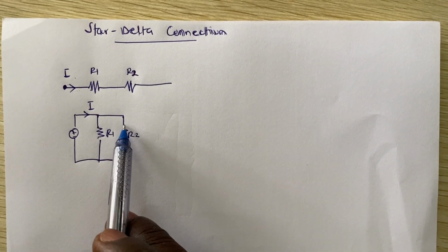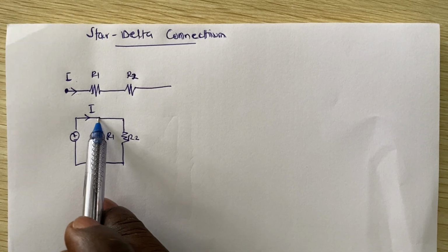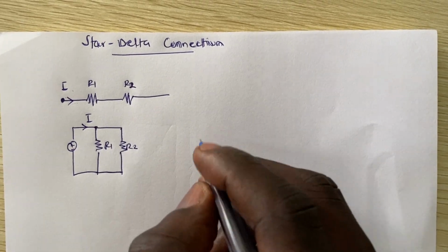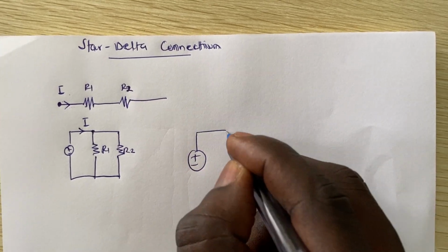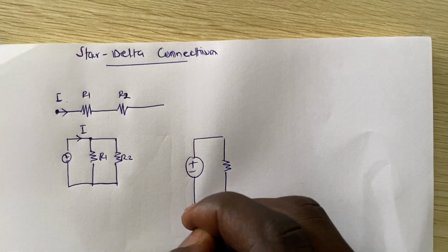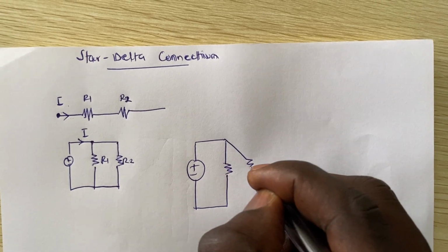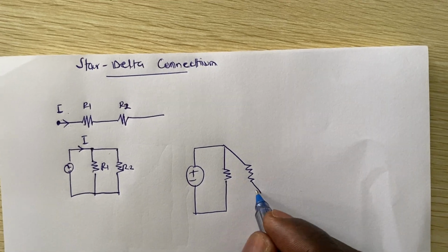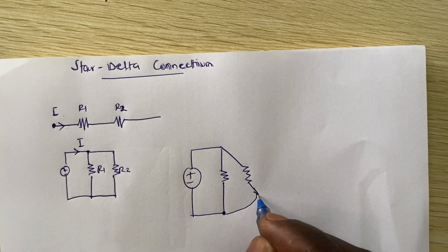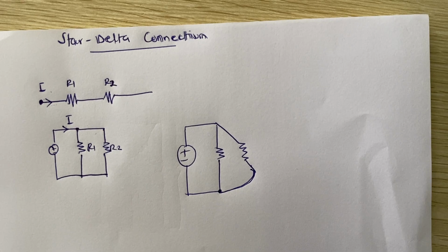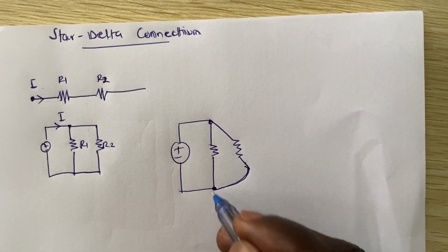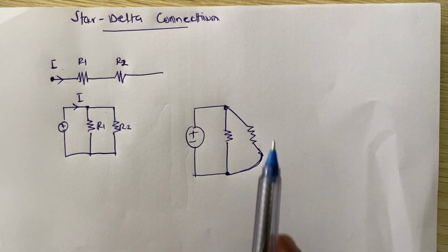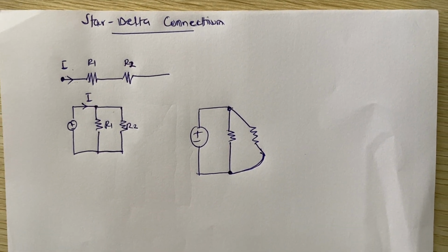So it means that if you consider these two, they share this common node, right? Because there is no element here, this is the same as drawing it as this. And in the same way we can do the same here, so it can be like this, it connects here, right? Because there's no other element. So when they share these two common nodes, 1 and then 2, without meeting any other branch where you can just navigate through them like that, then those two elements are in parallel, right?